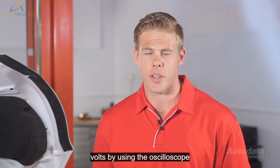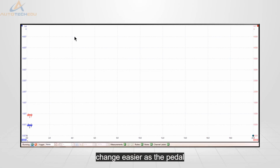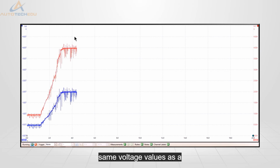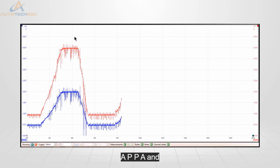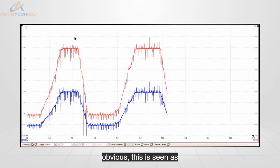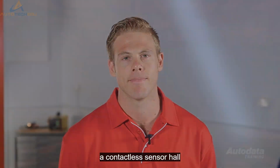By using the oscilloscope to monitor these values, we can see the voltage change easier. As the pedal is slowly depressed and released, we still have the same voltage values as the scan tool, but any discrepancies between APP-A and APP-B will become obvious. This is seen as an analog signal. The second type of sensor is a contactless sensor.